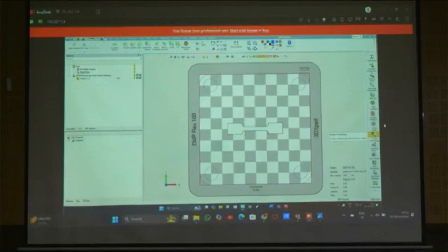The very starting position should be in the less contact actually. Suppose if it is like this, your entire surface is in contact. During the roller moving, the first part touching the build plate has a very high contact area. So the build gets failure. So what they suggested is to rotate the body by 5 or 10 degrees so that the contact can reduce. That is the recommended actually.